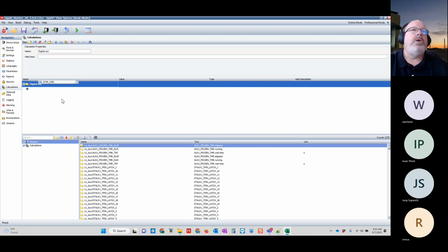When I look for tags within the flow computer that have to do with custom functionality, they have a common name associated with them, and that name is basically a custom val. And what we're doing is, if you're familiar with some of the other flow computers, maybe you're writing to a scratch pad or something else. In the FlowX, we're writing to a tag that's used to hold a custom value. And then we can determine if inside the logic, we want to use that custom value as our process value. And let's just use something as simple as meter temperature.